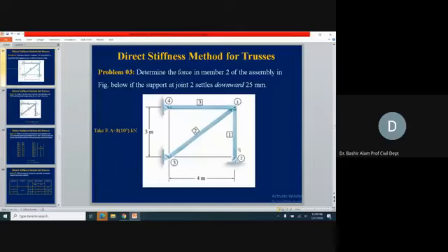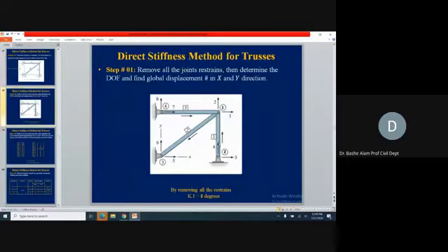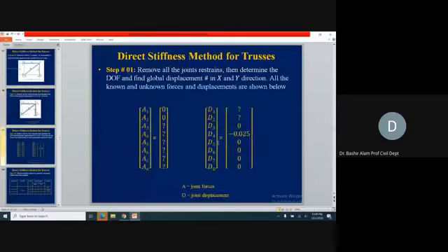So see what the displacement is here, D4, but it is in the upward direction. We come to the D4 location and put 0.025. Member lengths are in meters, so you need to put this also in meters, for unit consistency.